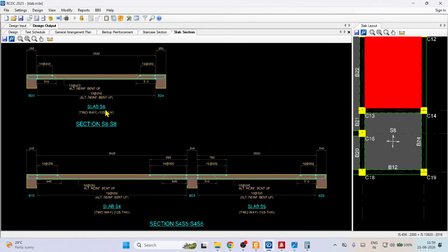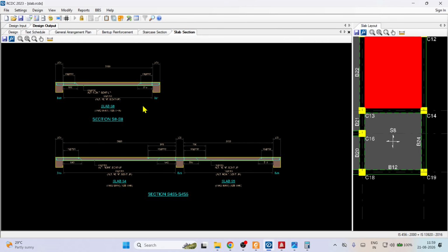Okay, so be careful what you are doing, but that much detail is not required in case of slab. If any kind of confusion is with you, you have to generate for yourself, see the reinforcement, make the table, give it to the site engineer, they can place the reinforcement on site. In case of slab, beam it is required, column only cross section is required, nothing much is required. Foundation also, top view is enough. Top view, and you can say that the longer side has this reinforcement, shorter side this reinforcement, spacing is this. So that is more than enough.